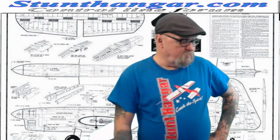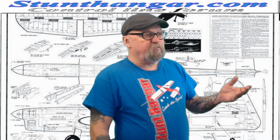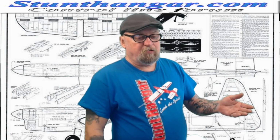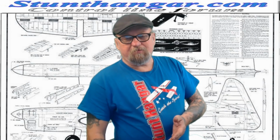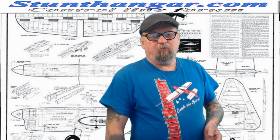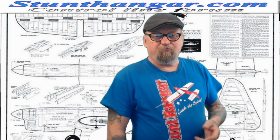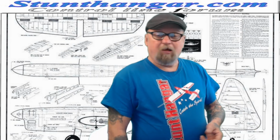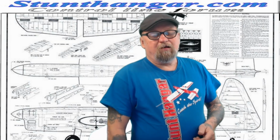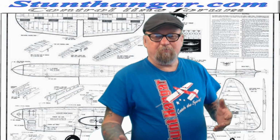Let's say the last airplane that I built had a 9-inch nose and had a PA-65 in it, and the airplane weighed 70 ounces, and it was tail heavy. Well, I have one or two things that I can do. Not build a 70-ounce airplane. That's the first thing. And that would mean that it would balance by lightening the airframe up more.